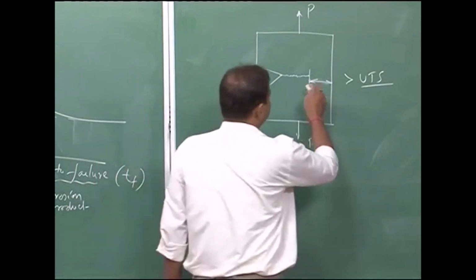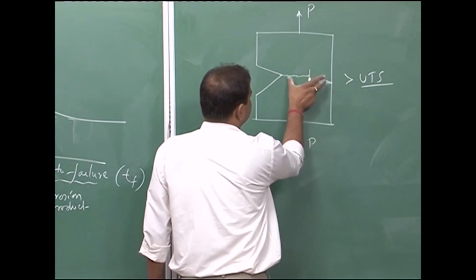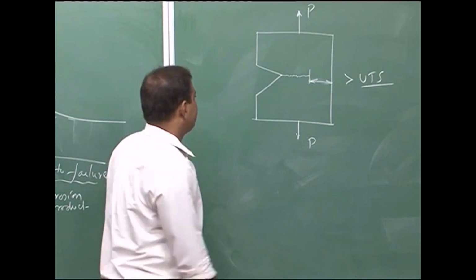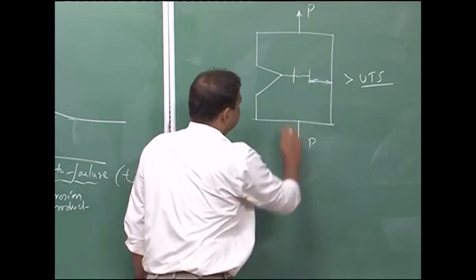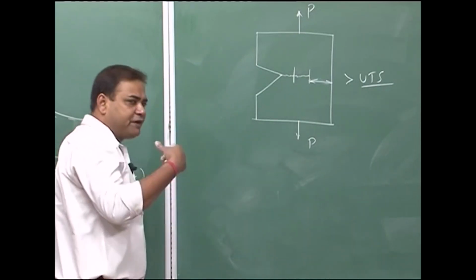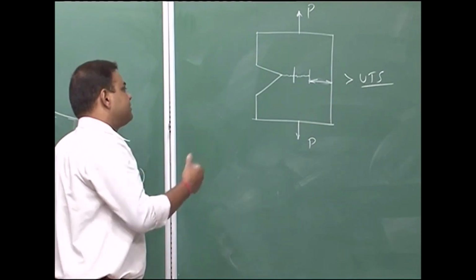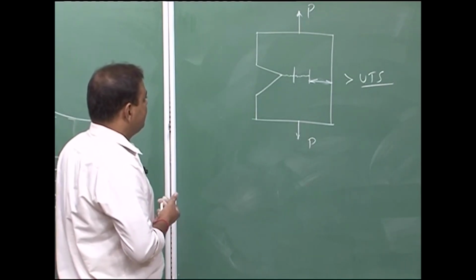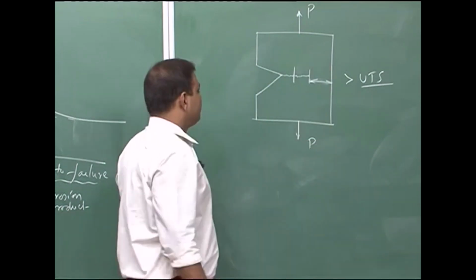Okay. So, that means unless we check the total time to failure, we would not be able to judge, for example, if up to this point the metal has gone and then we stop the experiment, whether the material would have a very good SCC resistance or whether it has a poor SCC tendency. So, that way we need to understand the total time to failure.